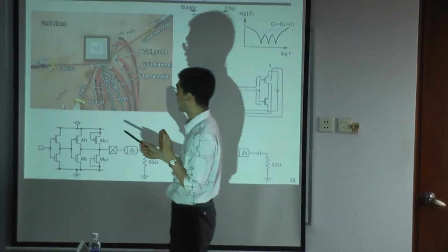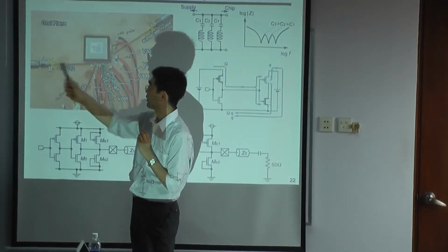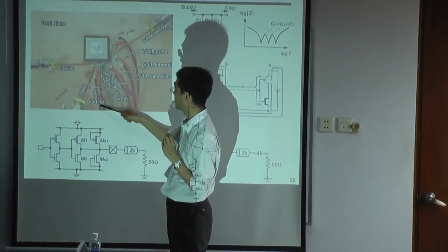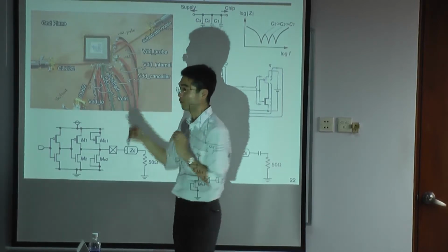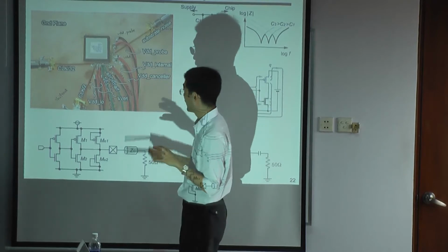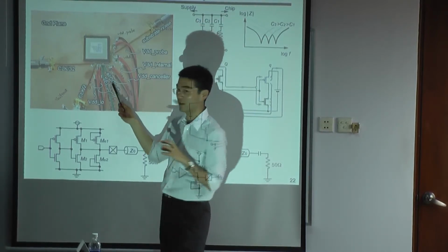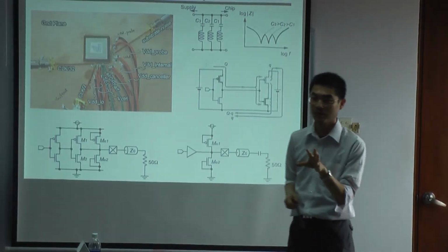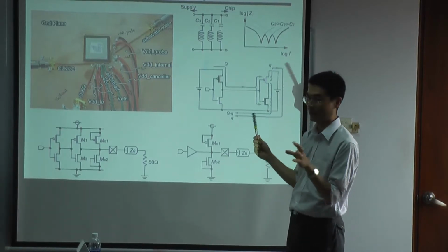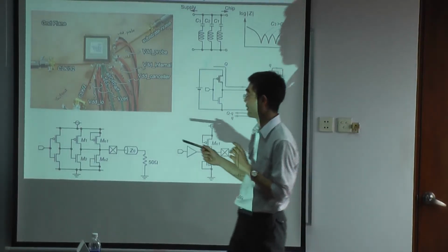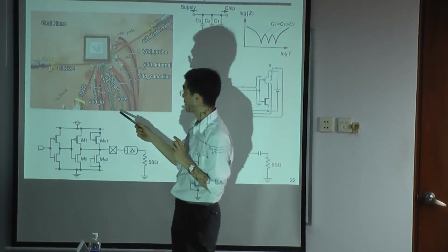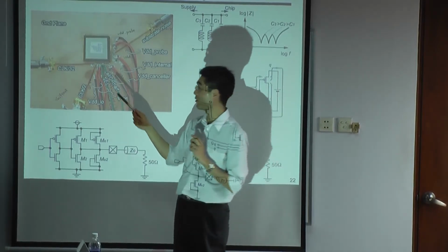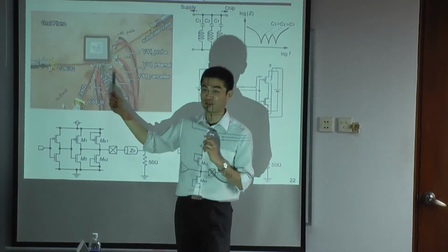In this case, we use this kind of 50 ohm connection only for the clock. For the power supply, we put a power supply island here, and we put many types of capacitors. And for DC signals, for example, this is the selector. It just selects the mode, for example, high speed mode and low speed. We don't have to have a high speed switch. In this case, these are just DC signals, so we just connect here. And of course there is an island, but we don't put any capacitors because this is DC and no current flows.